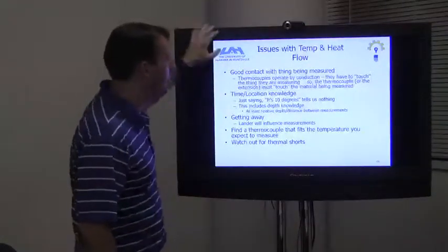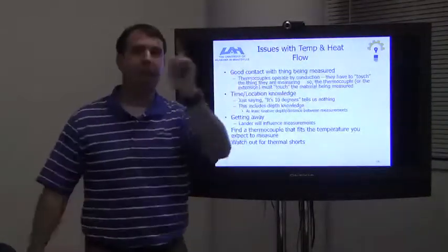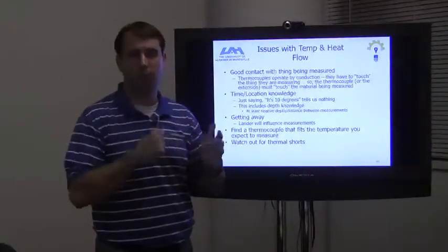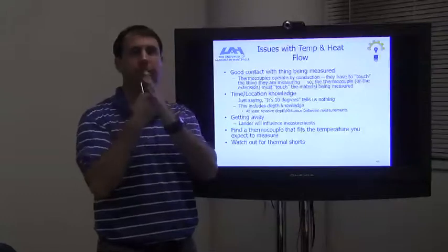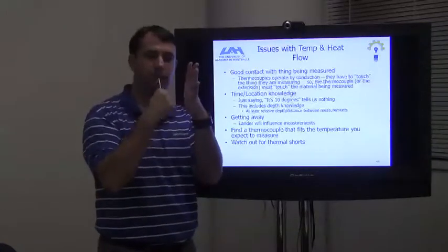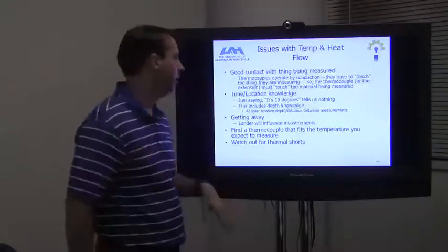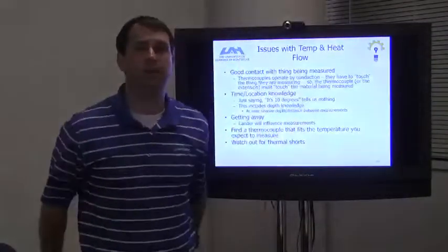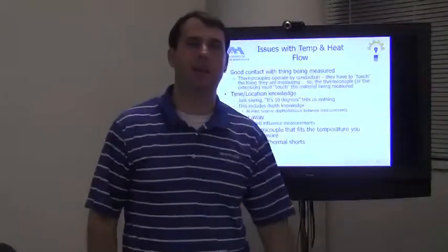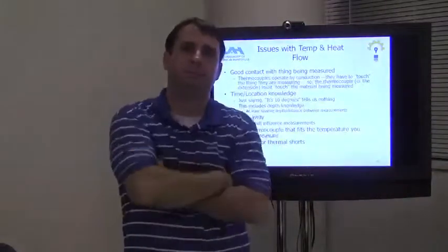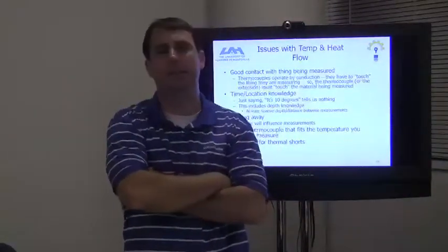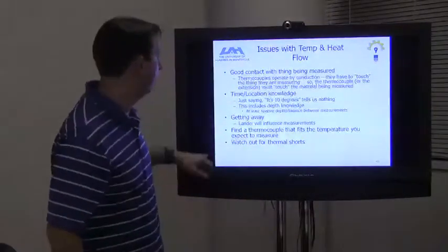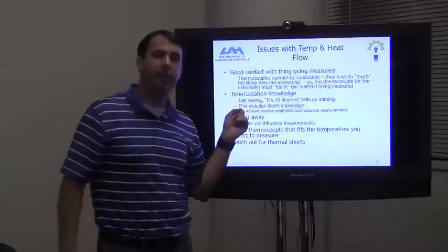With temperature and heat flow, you've got to have good contact. Temperature is touchy, and you've got to have good contact with whatever you're measuring. You want to make sure that you're touching it and that there's not a small gap, okay? That's the big deal. Time and location: it does no good if someone says, what's the temperature today? And I say, it's 10 degrees. And they go, well, where is it 10 degrees? I'm not telling you where. It's 10 degrees somewhere. So you need to know the location.